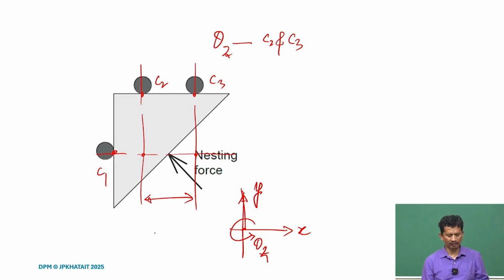So, if we try to rotate, the 2 constraints C2 and C3 with an offset always provide a rotational constraint. Whenever we want to give theta z motion, C2 and C3 are parallel with an offset, so they will provide the required constraint and the moment, and therefore it will not let it rotate. So, in this case again it is fully constrained in 2D for the planar case.